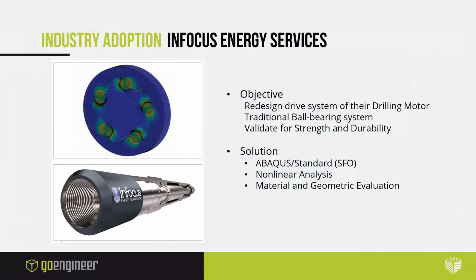Finally, the more recent case of the implementation of the Simulia technology on the 3DEXPERIENCE platform comes from Canada, from a company called InFocus Energy Services. They make machine tools for a plethora of applications. This one particularly, they were trying to fix a problem with one of their drilling equipment. So their drilling motors essentially incorporated a traditional bearing system that failed both in static and fatigue cases. They undergo a lot of bending loads, and they invariably ended up failing. So they couldn't rely on traditional bearings, so they had to design their own.